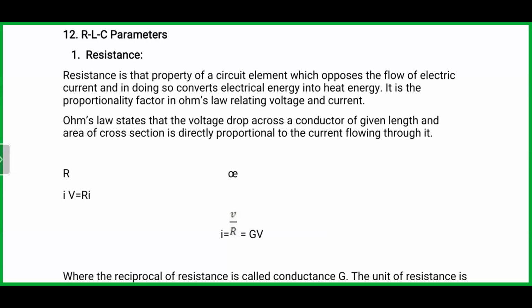Then you should know that your usage or your demand is beyond the circuit breaker's rating. So that means you have to go and increase the rating of the circuit breaker. What if the consumption is low, but you use a circuit breaker with a higher rating?